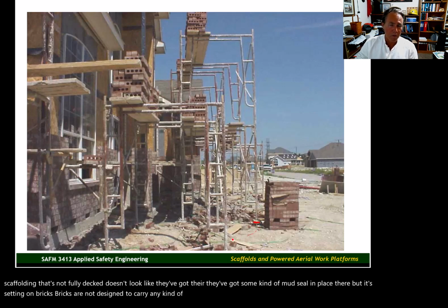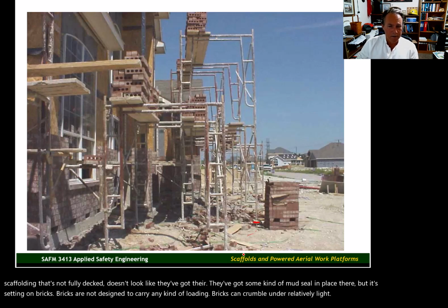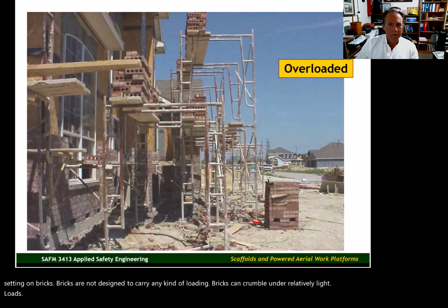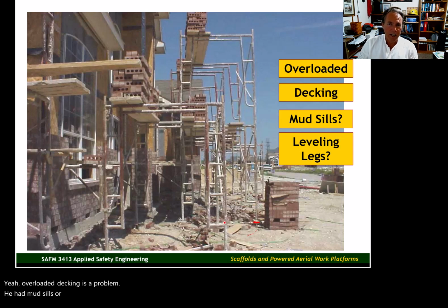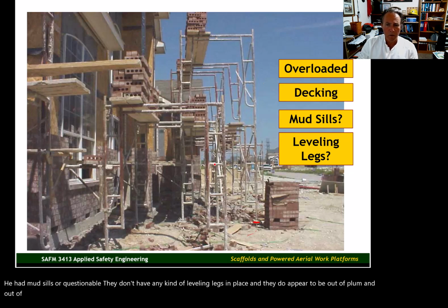Bricks can crumble under relatively light loads. And overloaded decking is a problem. Again, mud seals are questionable. They don't have any kind of leveling legs in place, and they do appear to be out of plumb and out of level, a number of the different scaffold sections that they have set up here.